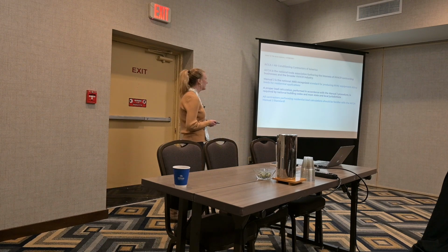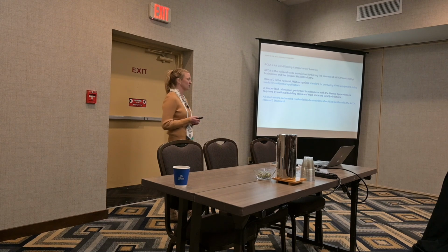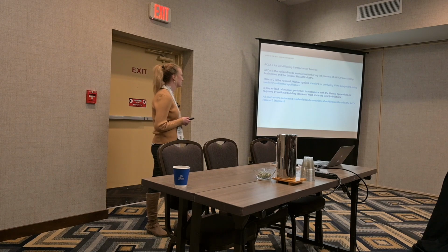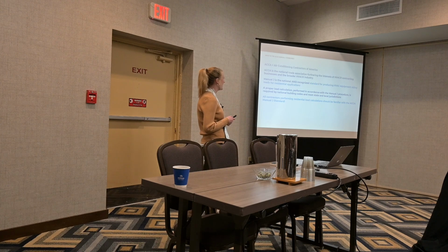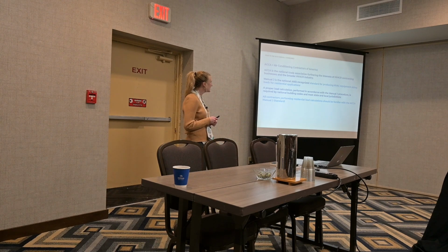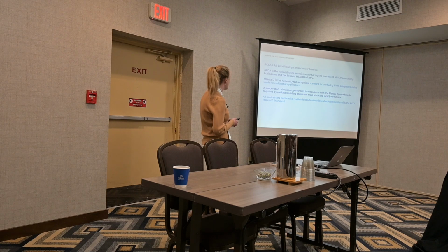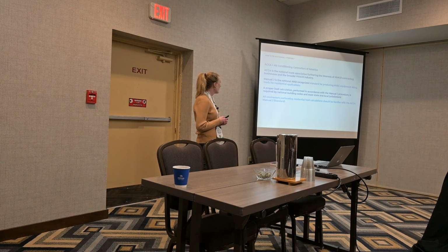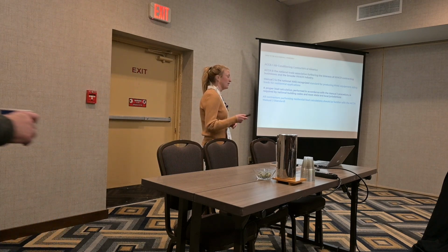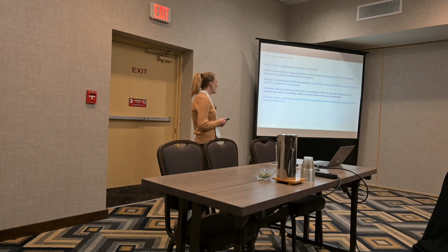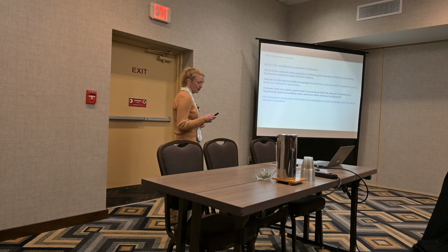So a proper load calculation is performed in accordance with the Manual J procedure. It's required by national building codes and most state and local jurisdictions. Manual J is the national standard for producing HVAC equipment sizing loads for residential applications. If you're not familiar with ACCA, ACCA is the national trade association for furthering the interests of HVAC contractors in the broader industry. So if you're a contractor performing residential load calculations, everyone should be familiar with the ACCA Manual J standard.